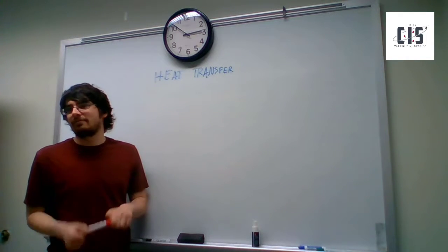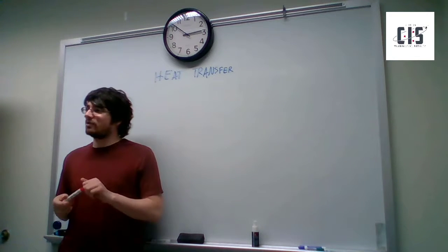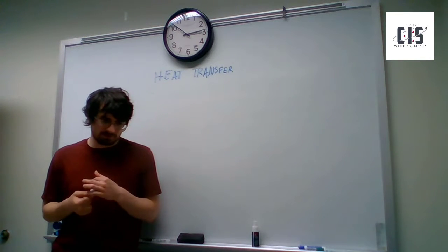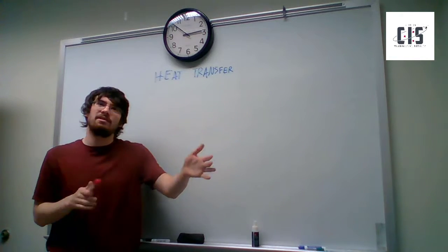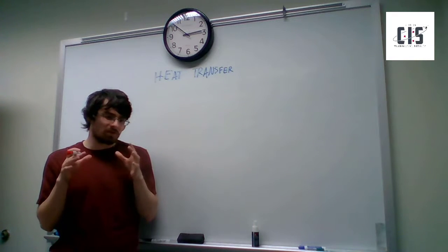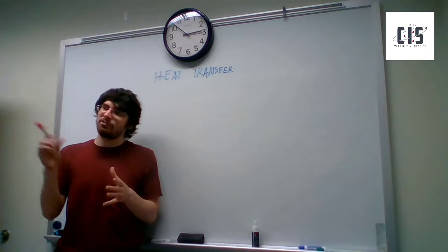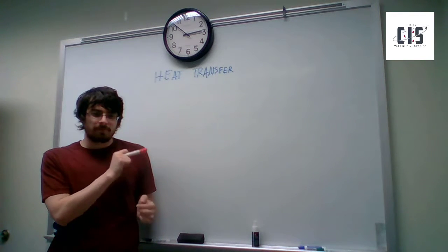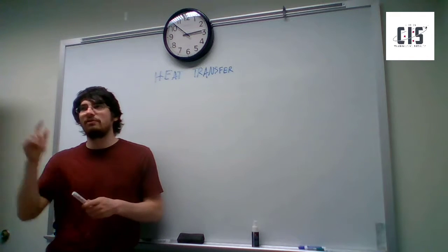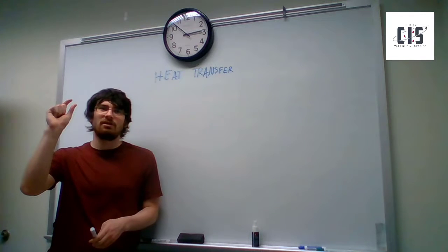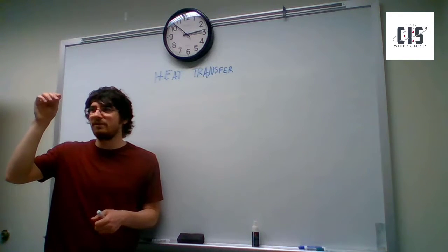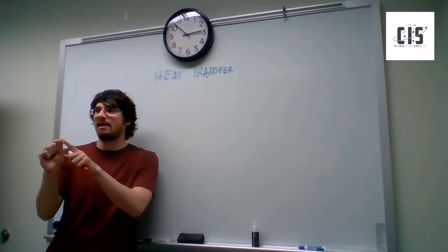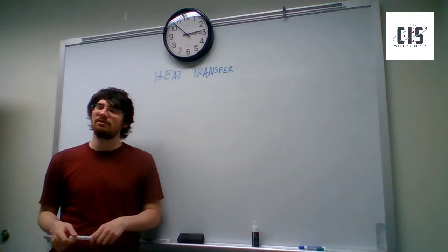Now, what uses would an entropy value have to a mechanical engineer? Some processes are isentropic, so that means entropy stays the same. This is nice because it helps you determine what the end state is from a starting state. Okay. So if you have a perfect turbine, for example, you have high temperature, high pressure gas going through it, it'll drop in temperature and pressure. And if you know the outlet pressure, you still need something else to figure out what the outlet temperature is. But if you know the process is isentropic, you can look at the starting temperature and pressure, density, or whatever, and say, here's the entropy of that state. And then you can find that entropy in just a table or in a program or something at the low pressure that you want. And then that'll give you all of the properties of the gas you need, or vapor, or whatever.